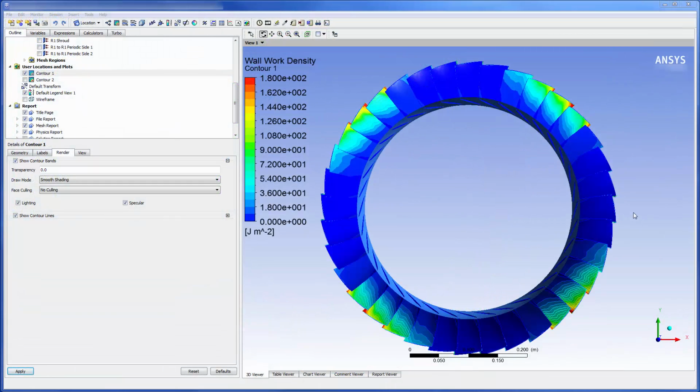As we can see, the harmonic balance transient method successfully describes the rotor's blade flutter at a fraction of the computational cost required for the time integration method. This concludes this demonstration showing you how to use harmonic analysis to describe the blade flutter of a compressor rotor.